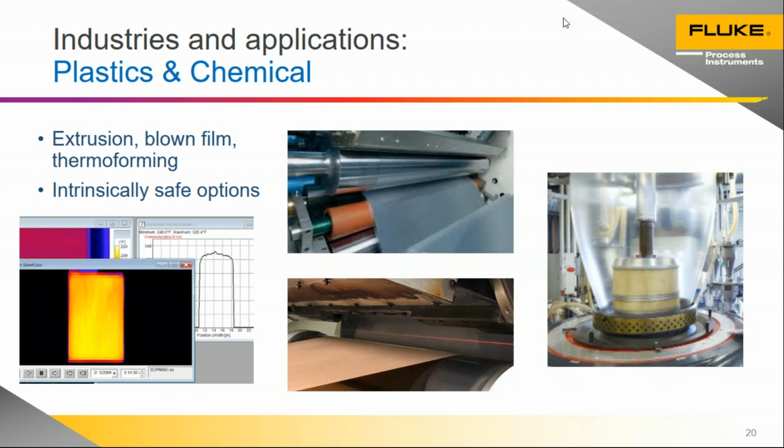Yeah, there's a couple of, I mean, it depends what kind of mill you've got, but quite often, at least in Europe, the line scanner's mounted in between each roller. There's a couple of things line scanning software can do, as well as just making more measurements, is we have the ability in our software to automatically track a changing width, which means if you want to analyze center left, center right, left and right, we can apply sectors or measurement points that actually track automatically either for different recipes or changing widths, but essentially auto track.